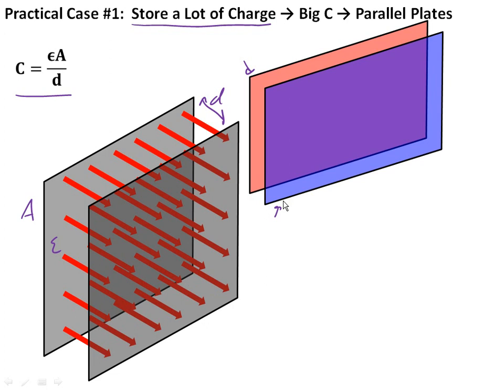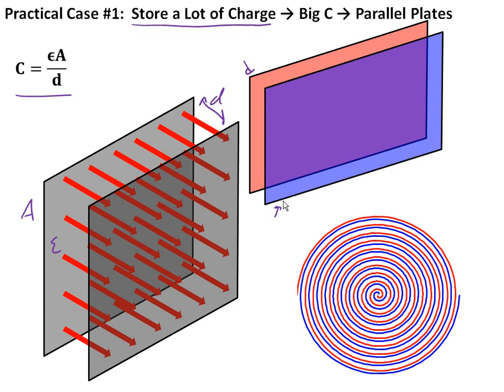But of course you never see these giant plate capacitors sitting around anywhere unless you go into sort of an ancient laboratory. So what you really do to make high capacity capacitors, once you have the thin sheet of plastic with metal on both sides, is you roll it up into kind of a cylinder, the way you'd roll up a jelly roll, and this gives you a very large area in a very, very small volume.